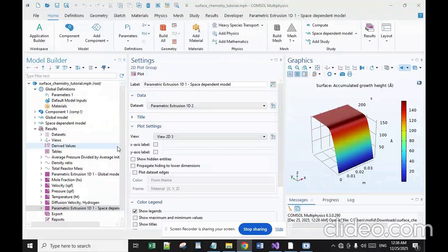Many journal articles and commercial tools use the term reduced pressure CVD, especially for single wafer tools, in place of LPCVD, which dominates for multi-wafer furnace tube tools. Reduced pressures tend to reduce unwanted gas phase reactions and improve film uniformity across the wafer.